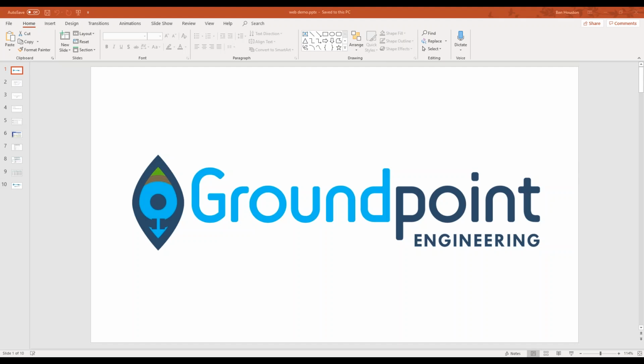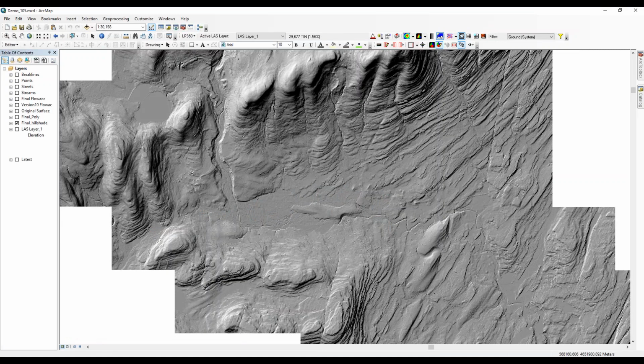So I wanted to take a few minutes to show you a couple of projects that illustrate what we're talking about when we talk about high resolution drainage and how it works. Ultimately, what we're talking about is using digital topographic data from sources like LiDAR or photogrammetry or even drones to map out preferential flow paths on the surface and then be able to map the drainage catchment areas.